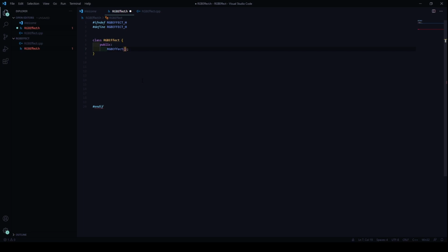This will accept three parameters. We'll call them int R pin, int G pin, and int B pin, representing the red pin, the green pin, and the blue pin for the blue leg of the LED.